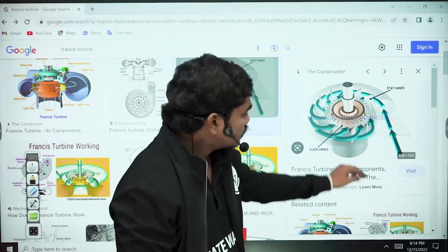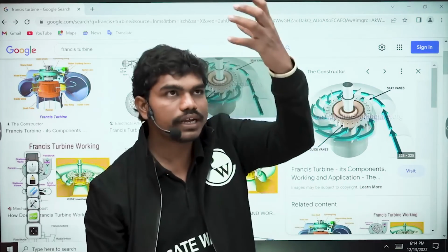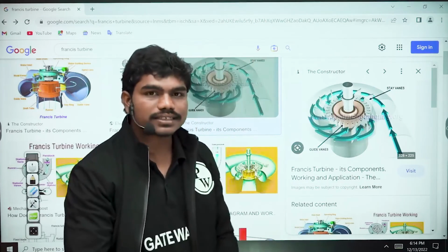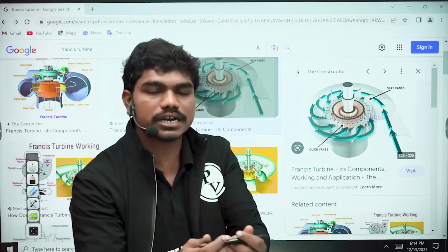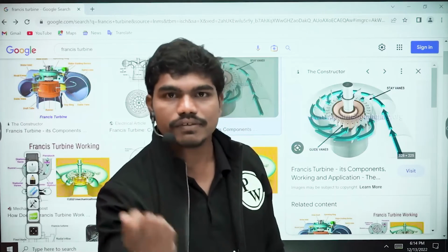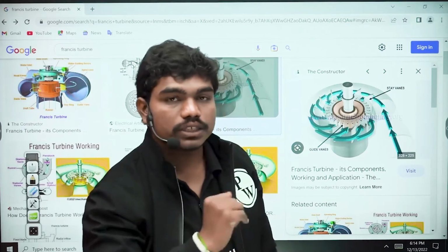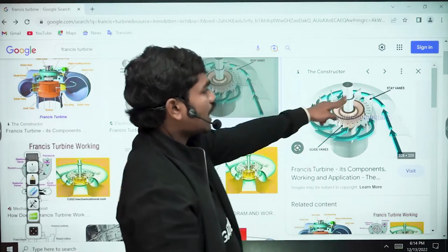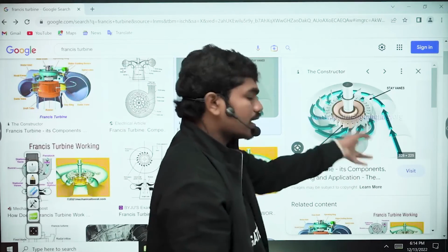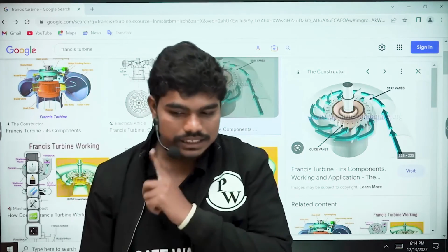But the small energy that remains, with fluid coming vertically in this direction, can rotate an axial turbine, like a fan placed at that location, because high velocity fluid hits the blades. So normally this shaft is sometimes coupled with the Kaplan turbine shaft, so that some excess power can be generated.